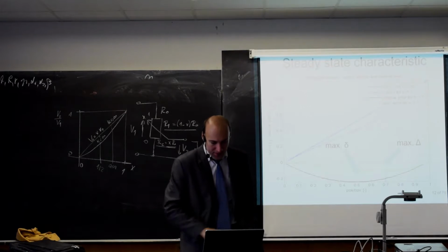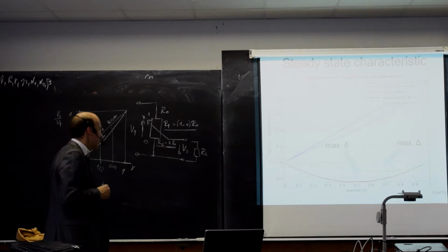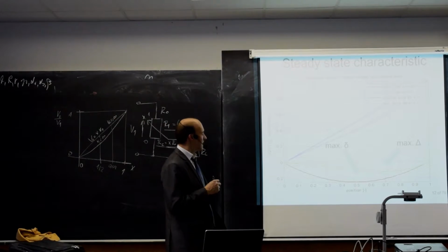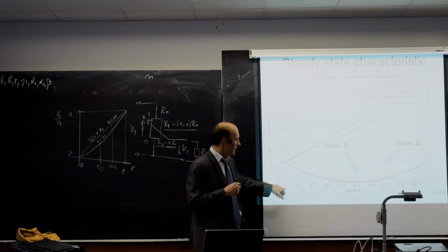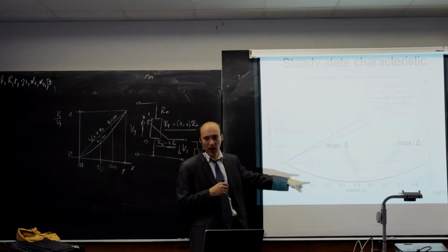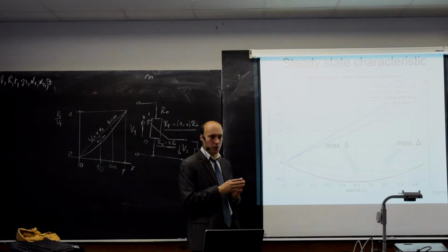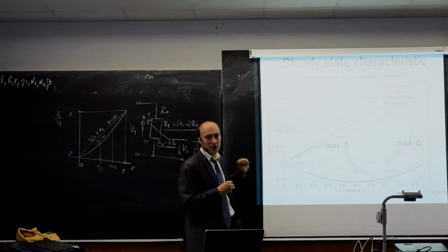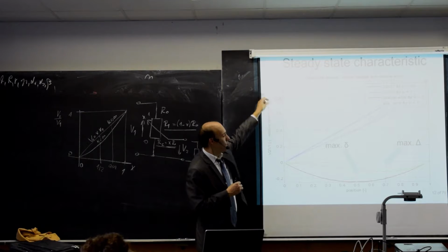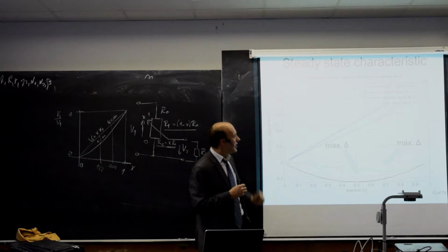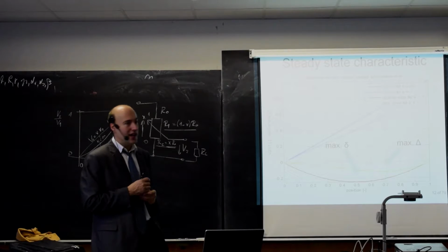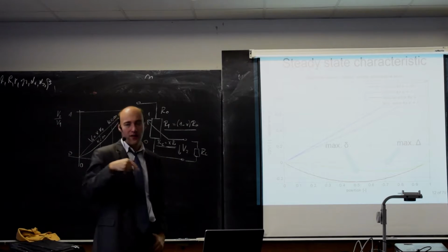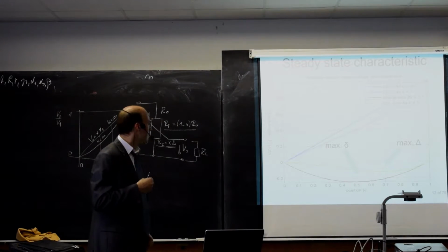To show you some measured data, here is how it looks. Those are data for a sensor that's similar to the one before. On the x-axis there is position between 0 and 1, so between minimal and maximal position, so full scale. Here we have the ratio between voltage V2 and voltage V1, so between 0 and 1. The blue line is for k going to infinity, so that's the linear response. This is what you will have if you have a voltmeter with a high input resistance.